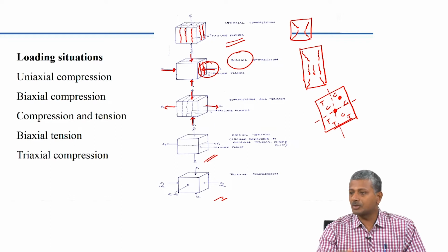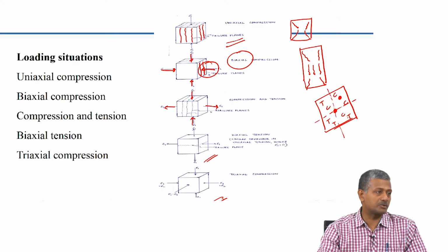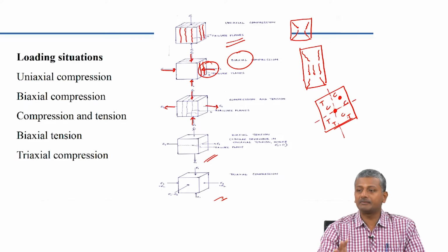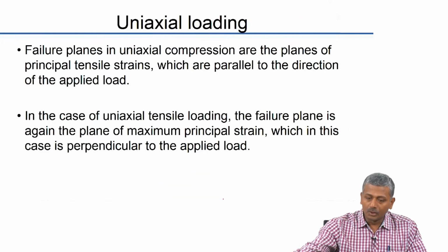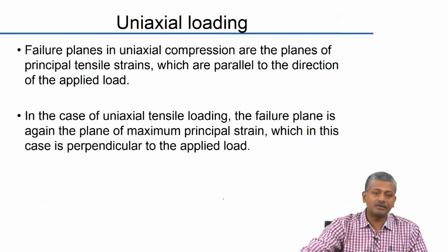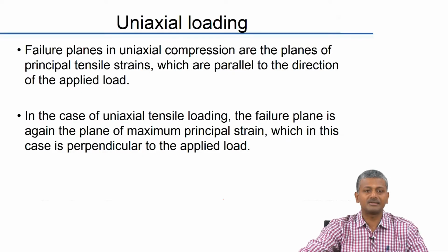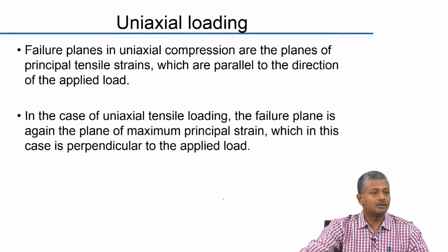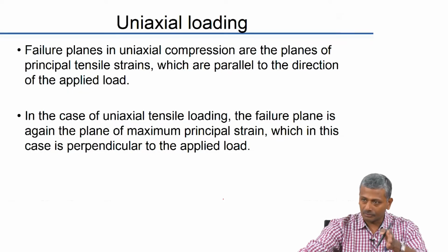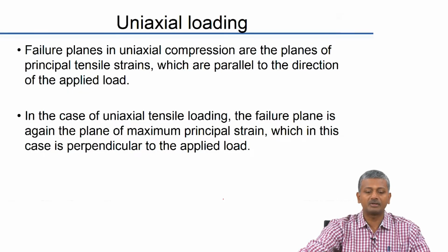Okay. But that is not something we contend with in real life unless we have a hydrostatic pressure. So, for the most part we will be dealing with biaxial states of compression and tension. So, it is useful to look at the biaxial stress interaction curves. Of course, what I have put in the slides here is again the same discussion as what we saw from the diagrams, so I am not really going to expand on it further.